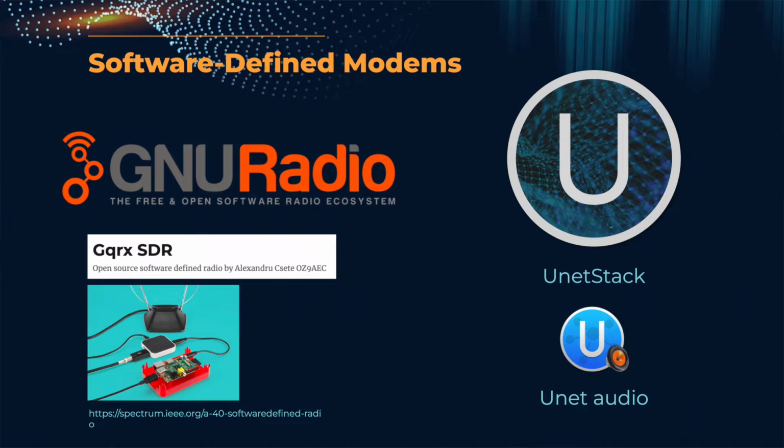But in the case of underwater, there is some software, but if you take GNU Radio and try to do an underwater network, what happens is if you're using RF, yes, it probably will work straight out of the box. But if you want to use anything meaningful, you want some range. Even in the pool, RF probably won't work more than a couple of meters. But if you want to communicate with your vehicle to tell it to do something, you might want something that propagates slightly longer, either light or sound.